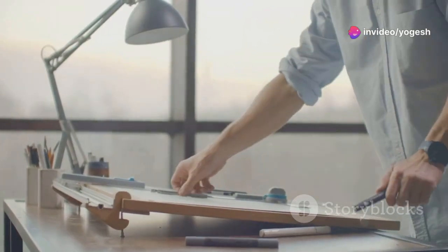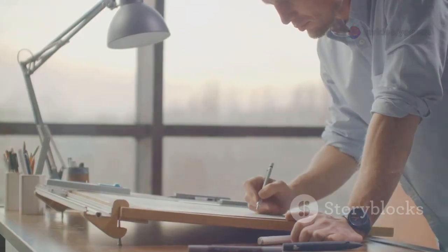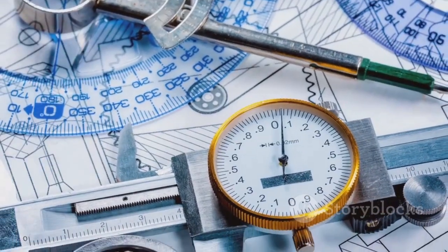Imagine a box with a lid propped open at 45 degrees. From the top, the lid looks short. From the front, it's a line. Neither shows its true size. But if you look straight at the lid, perpendicular to its surface, you see its real shape. That's what an auxiliary view does.